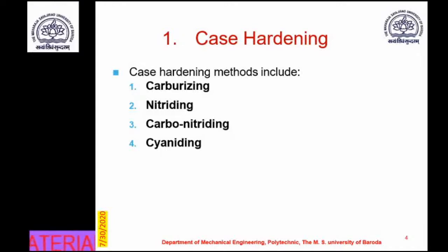So what are the different methods for surface hardening? One of the methods is called the case hardening method. And in case hardening we have different methods based on the raw material that is used for generating the hardness on the surface.